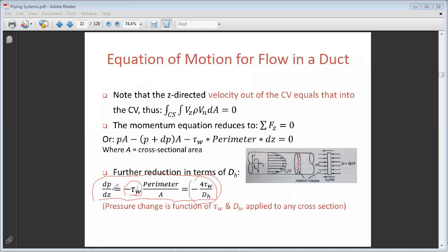Okay, and these losses can sometimes be calculated by analytical solution. For more complex cases, which we will see later in this chapter on turbulent flow, we have charts. Moody charts, if you remember, will allow you to calculate the pressure drop, or if you know the pressure drop it will allow you to calculate the other properties, like diameter or flow rate, etc.